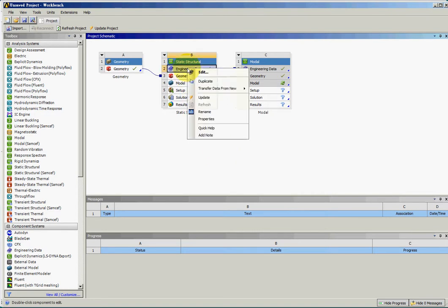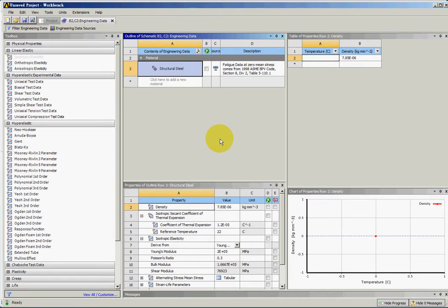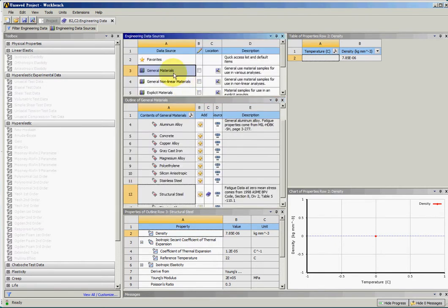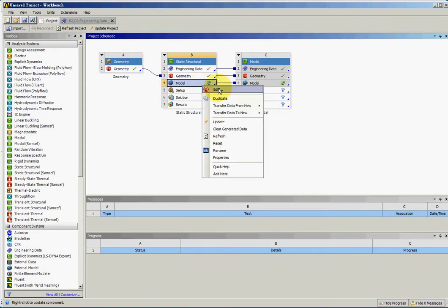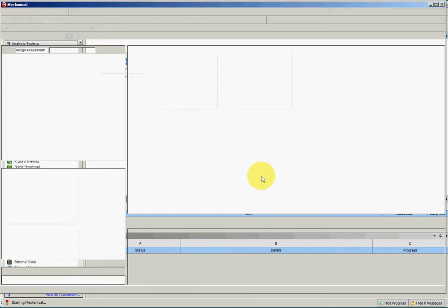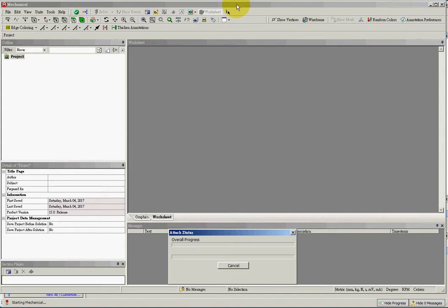So then I will edit material by entering material procedure and change to data source and choose general material. I will choose polyethylene. For CD plates, I wanted to choose polycarbonate PC, but there's no polycarbonate in the library, so I choose polyethylene instead. So now I'll enter ANSYS mechanical interface. And actually, ANSYS mechanical is a procedure where all the CAE procedures are implemented.